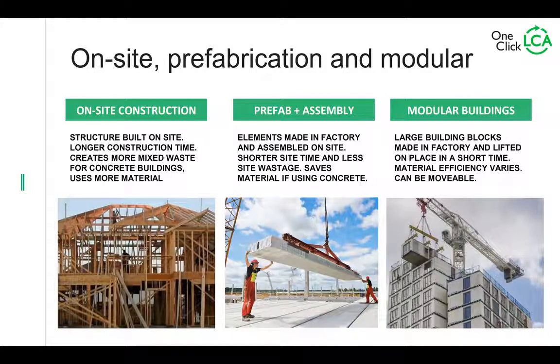It typically leads to longer construction time, and it may create more mixed waste, because separating the waste streams can be a bit more tedious when you are building on a site. In particular, for concrete buildings, this uses more material. However, for timber buildings, because much of the on-site construction is thin frame, as you can see here, and not massive timber, it actually uses less material. So no one size fits all rule here.